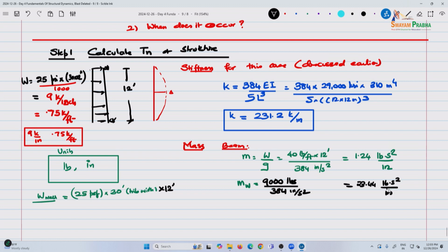Now, it's a pretty significant thing. In a slab design, you would include it because that's a weight. So, the concept is the mass contributes to the inertia. Whether it contributes to your stiffness or not is the question. Here the inertia is coming only from the beam.